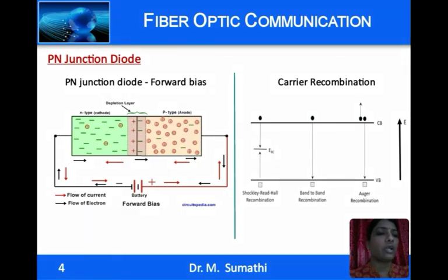In Shockley-Read-Hall recombination, an intermediate level is present due to crystal defects or foreign atoms. So, here recombination centers or traps are established. When these centers are closer to one of the band edges, then recombination probability is lesser, but when it is midway between the two, recombination possibility is higher, but the energy is less and therefore, the excess energy is released as phonons or vibrations.